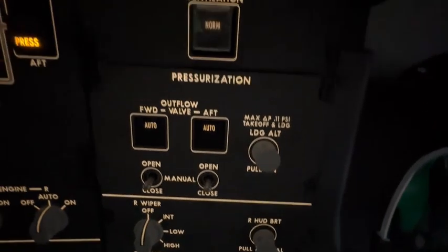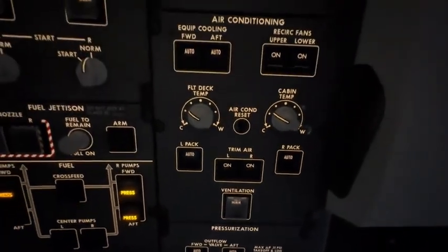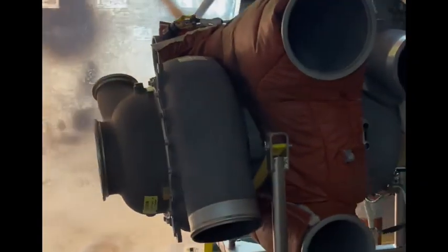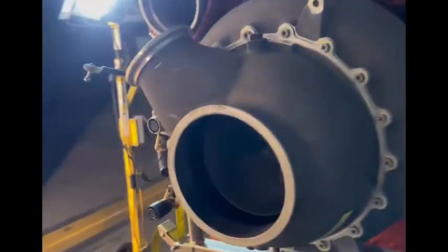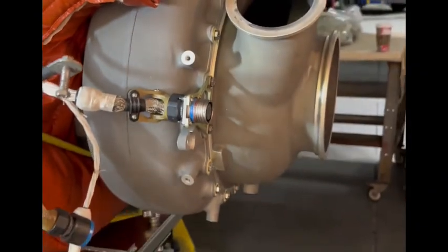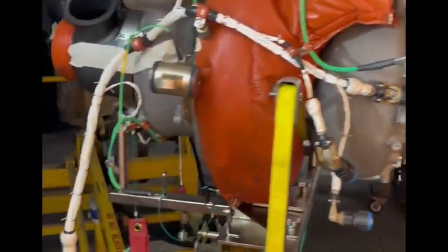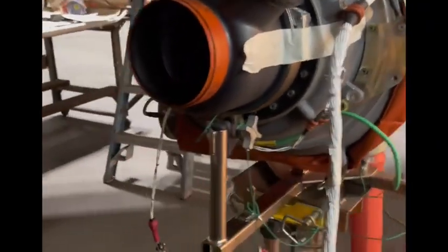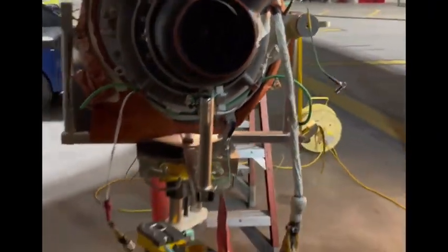And since we're on pressure, now let's talk about the air conditioning system. The air conditioning system on the 787 is one of the most unique things about it. It does not run on any kind of bleed air. It runs on electricity. The 787 has four CACs, cabin air compressors, electrically driven, but working much the same way as a conventional aircraft within its system. The only difference is it's not taking air from the engines or the APU. It's generating its own power via electricity. To be honest with you, it's kind of similar to your household AC unit.